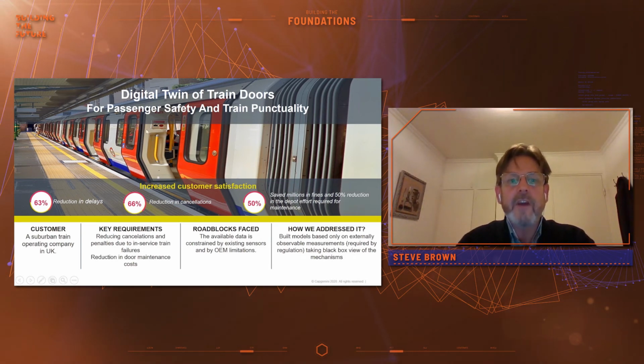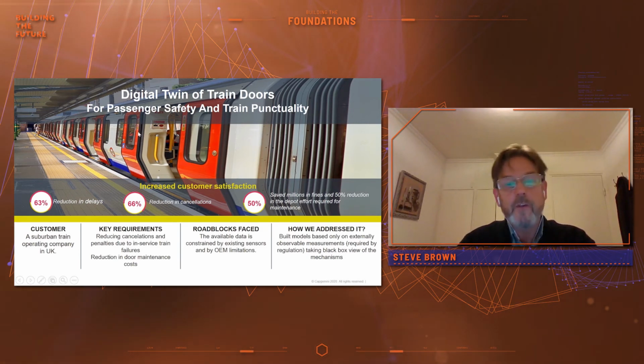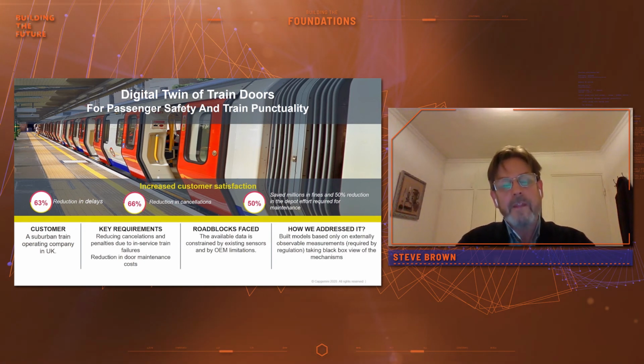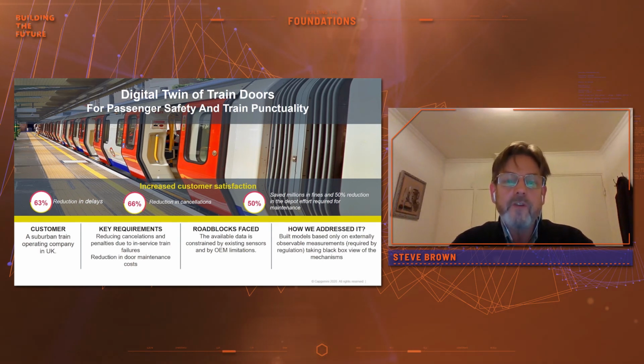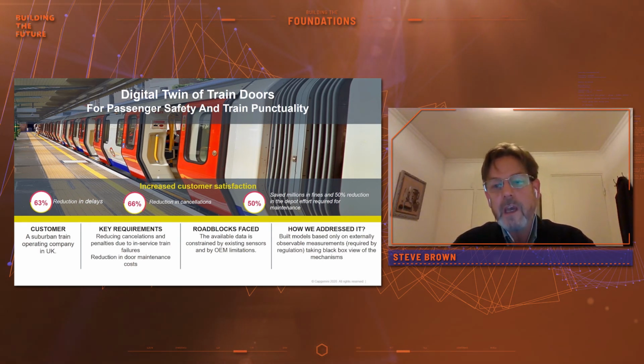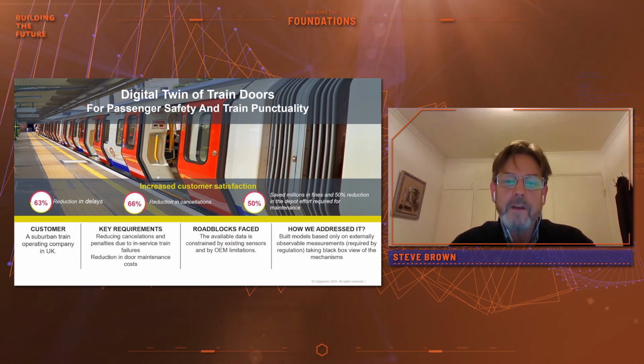But we had the data related to the assets, and we had key sensor data that allowed us to predict failure based on how fast the doors were opening and closing. This then allowed us to predict when they needed to come out of schedule, so that we could schedule them into the depots to repair, and then not only schedule them into the depots, but also to predict which assets they might need to do the repairing.